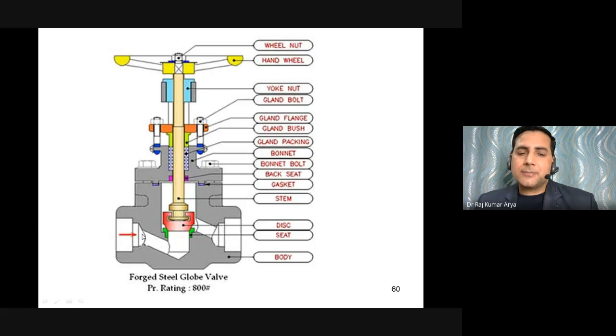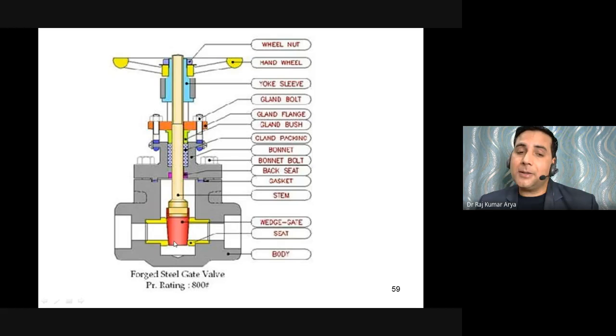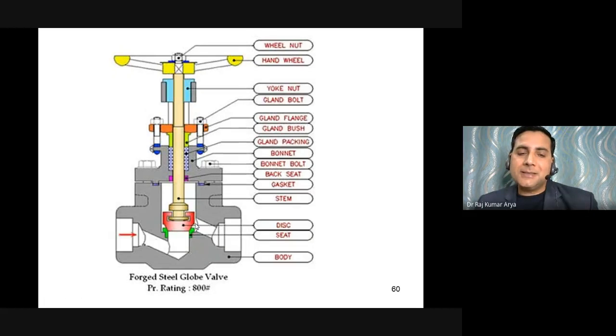Now in this case, this is going to hit vertically upside. So in this case, the damage of this seat would be high. This case would also be high if it is not fully open, sorry, so it will hit this particular portion of the gate. So it will be hitting at 90 degrees here, this side. Here, the 90-degree change is decreased. This is also getting hit by the 90 degrees, but you have already changed the direction here one time. So therefore, the magnitude of the impact on the seat would be low as compared to the previous one.